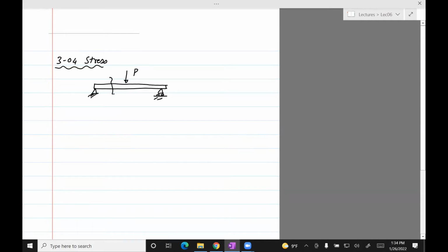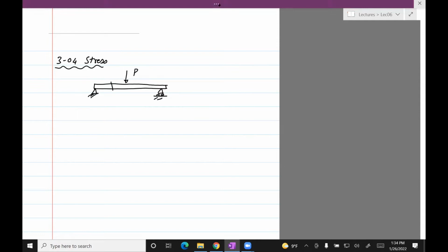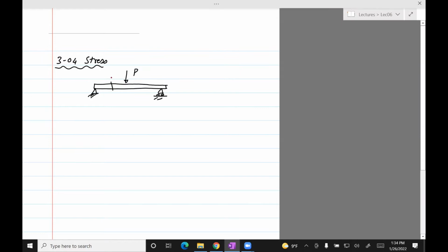We basically cut the beam at some section because perhaps we know that if it fails, it will fail at that particular point, because maybe there's a defect there, or maybe there's a weld, or maybe there is some attachment which connects the left side with the right side. And so we want to find the shear force and bending moment diagram there. And that's what we did so far: V of X and M of X.